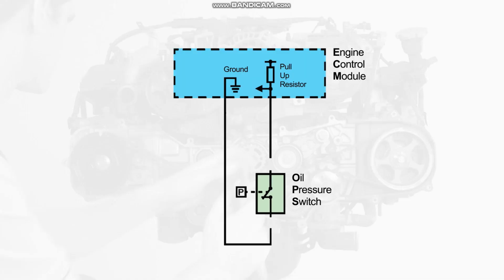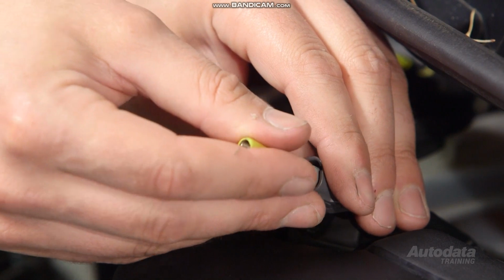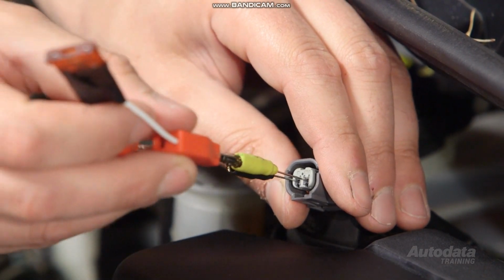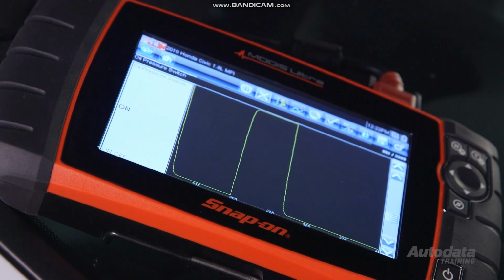If the voltage is correct, the most likely cause is the sensor itself. This can be confirmed by connecting a fuse jumper between the 2 sensor terminals whilst observing the scan tool readings. If the parameter changes, then the sensor is the fault.